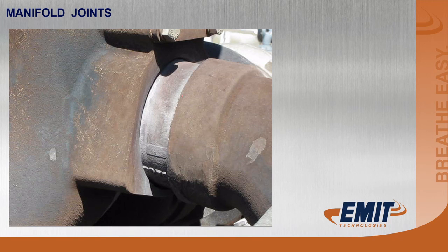Wastegates. Anytime you have a wastegate dump like this, as this again is on a Waukesha, you'll see the same thing on Caterpillar engines or any other engine manufacturer. This is supposed to swell up and seal as the engine gets warmed up. As this collar in here, the spool, gets warmed up, it's supposed to seal on this surface right here. If that does not seal when the wastegate is dumping, it will pull oxygen into the exhaust stream and cause poor catalyst performance on NOx reduction.